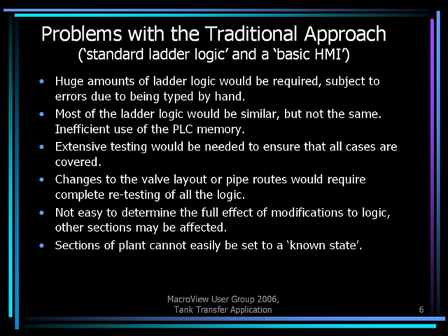The problems that you might have with a traditional approach would be standard ladder logic, lots of normally open, normally closed contacts, leading into result gates. A whole lot of selection criteria for selecting a tank in a different mode would be very large, very cumbersome, and prone to a lot of error because it would all be typed in by hand and would be quite difficult to test, we felt. And also with the fact of bits of equipment being taken on and off at will by the client during the design, we would be going back to scratch quite often.